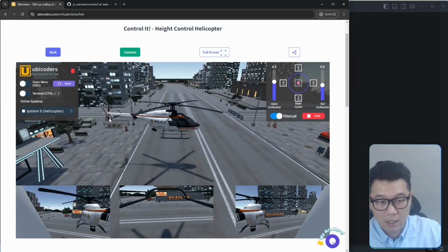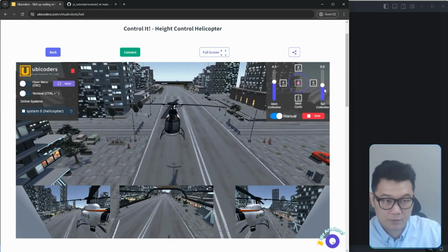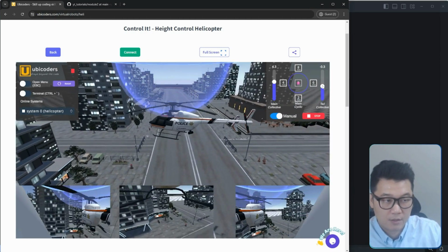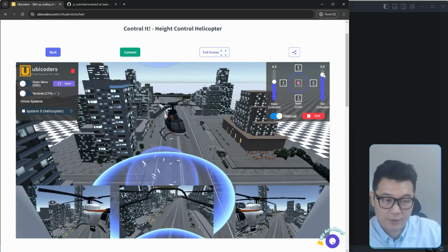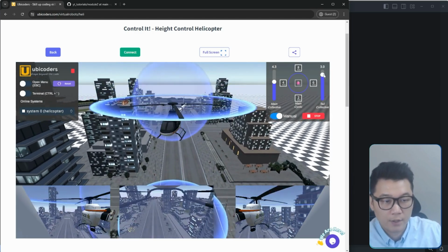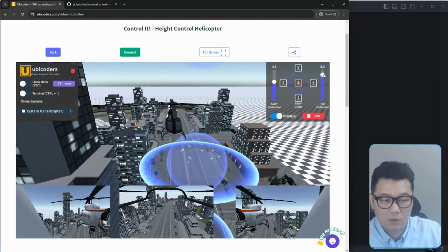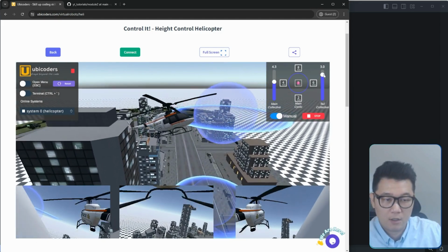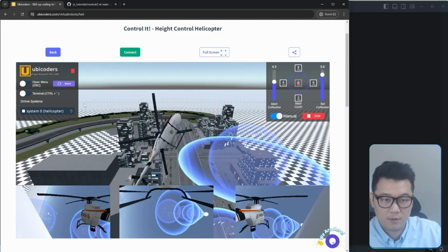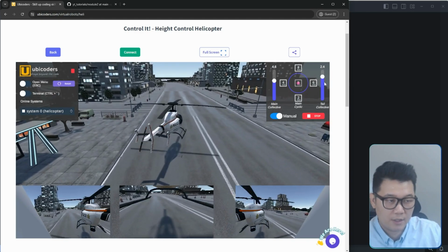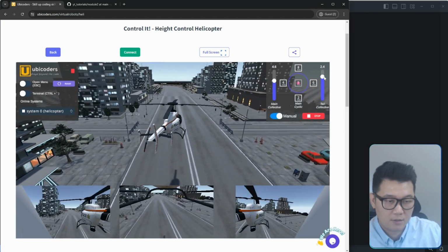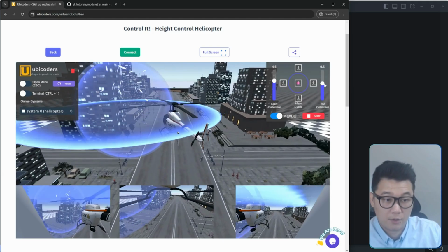However, there's a tail rotor doing nothing there. Although it's rotating, there's zero collective pitch angle for the tail rotor, so you just need to increase this to compensate for the reaction torque. Then it stops, and it will come back to there. Okay, that just crashed it. Let me reset that, do this again, and increase the tail rotor pitch angle together. Then I can control the heading of the helicopter like this.